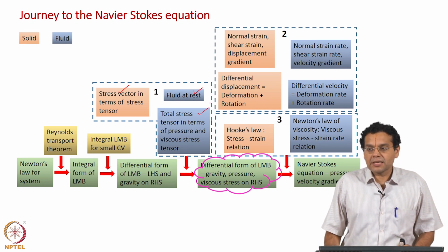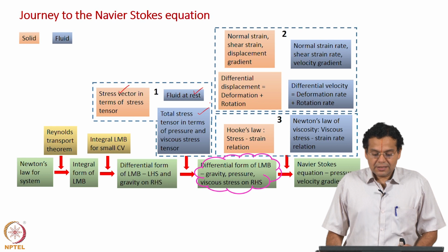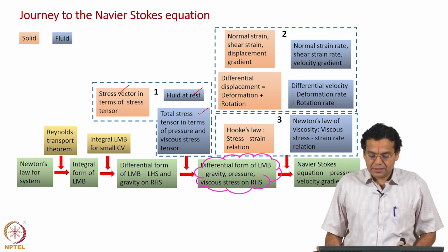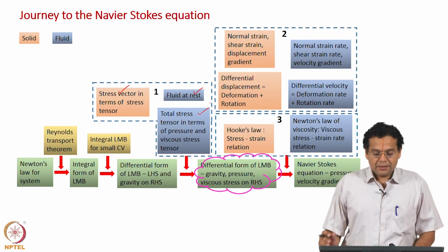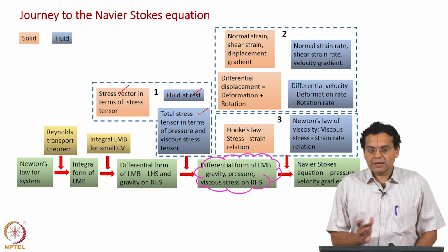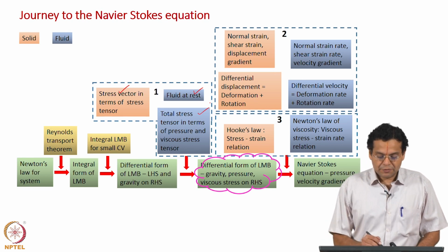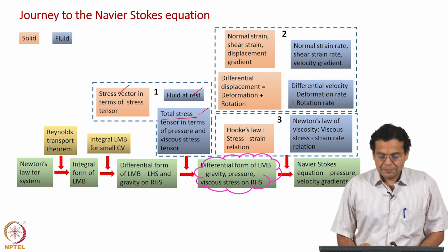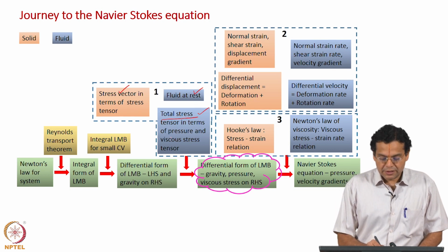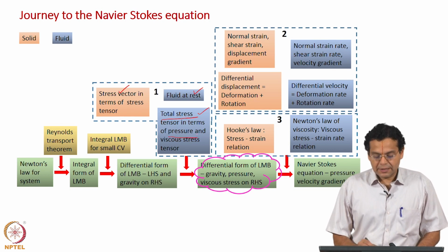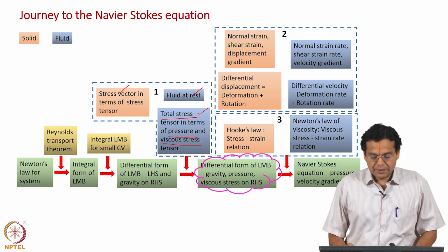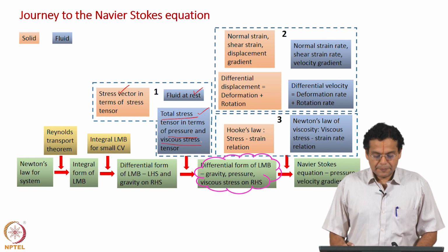In that, first we discussed fluids at rest and the hydrostatic stress, and then we said in the case of fluids there is a stress under stationary or rest condition. When it flows, additional stresses are there. So, we introduced the total stress tensor as the sum of the contribution from pressure and the contribution from viscous stresses.